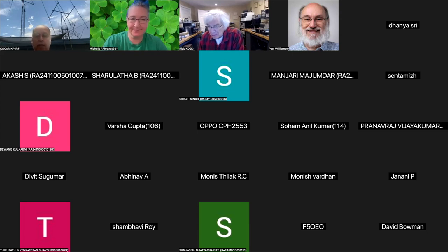Locally, we're using KiCad, or KiCad, depending on where you come from, for PCB layout. It's a very intuitive piece of software. It's a free download. And certainly there don't seem to be any limitations that would stop us putting FPGA or processors on board those. We've used the STM32L4 that I think you mentioned in an email to me earlier in another part of the project. So we know that one performs very well and is comparatively low power. It's just a question of does it have enough processing power for this particular application?